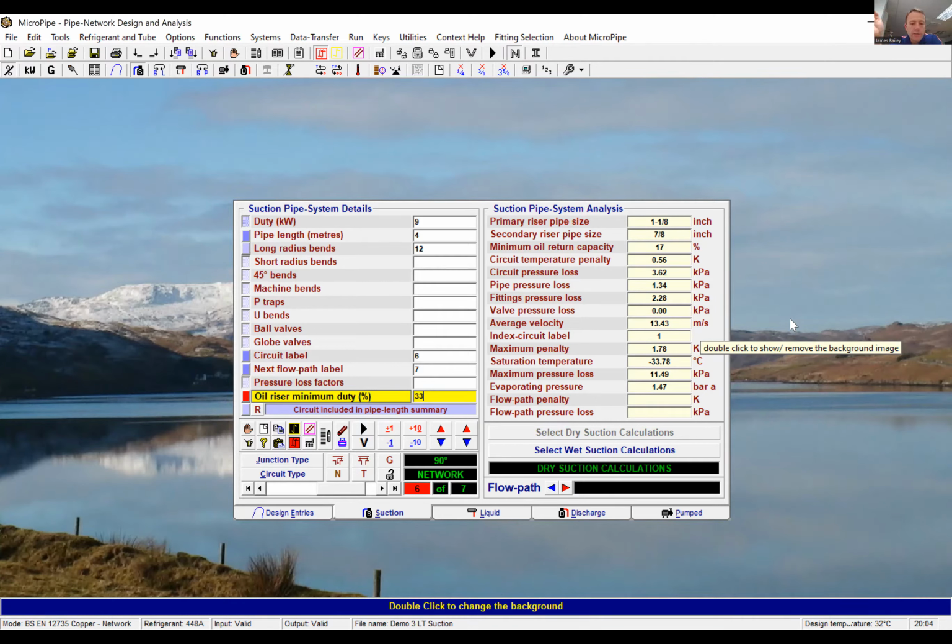So not just in the summer months where 58, 60, 70, 80% oil returns, you're going to be pretty good. But one thing I would say is, due to defrosting, we do a lot of defrosting on demand in the UK, and we've shifted a lot of defrost patterns to when energy is a little bit cheaper as well, especially on frozen, where we're using electric heaters effectively. So there's ways around what we've been talking about, but for me, this is how I would design.